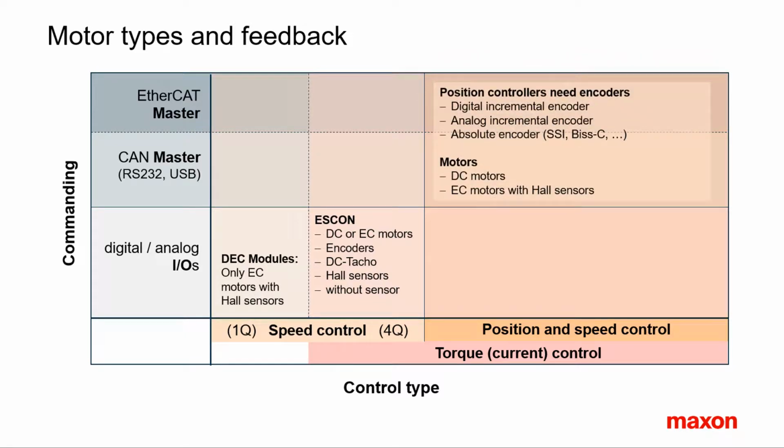Feedback from encoders is mandatory for the positioning controllers, be it EPOS or MaxPOS. Depending on the exact controller type, a variety of encoders can be used. EPOS and MaxPOS can power brushed motors or brushless motors with Hall sensors.